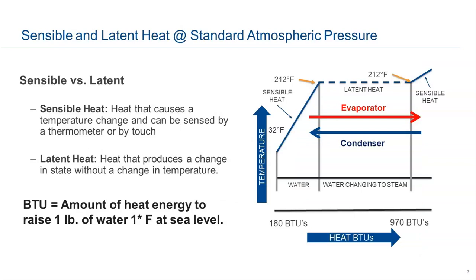So I'm sure a lot of you have seen this chart before. I know the first school that I went to had this chart, and it's a piece cut out of a lot larger chart. So you would have another line here that would be changing ice to water, okay? And this chart is based on atmospheric pressure, which we know is 14.7, unless you're in Denver, Colorado, and they'll let you know right away that it's not 14.7. And I went back the next time with some high altitude PT charts. But for this conversation, it's going to be 14.7.